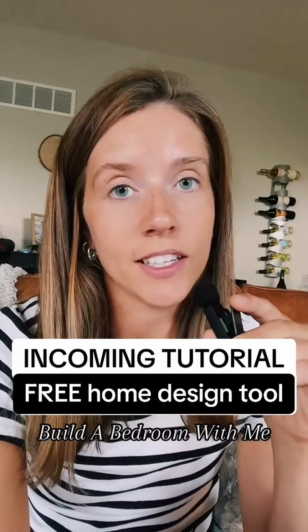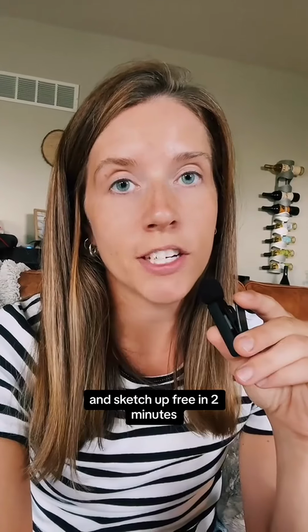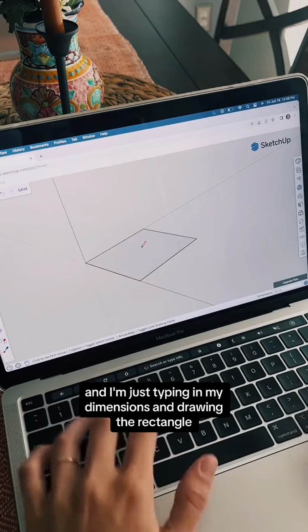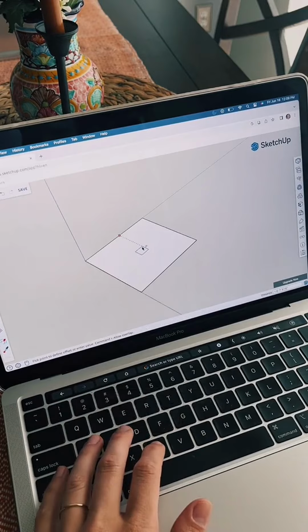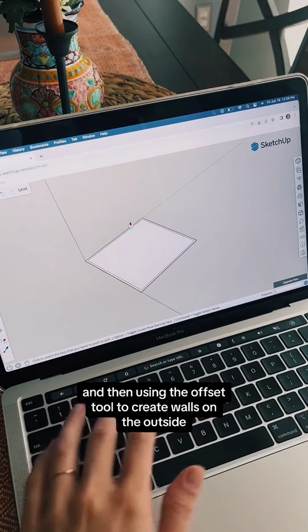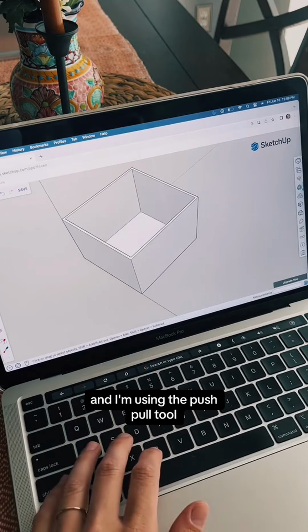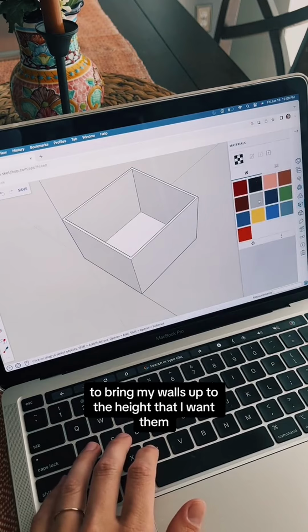I'm going to show you exactly how I model a 3D room in SketchUp Free in 2 minutes. Okay, so here we're starting with a rectangle tool, and I'm just typing in my dimensions and drawing the rectangle the dimensions that I want it. I'm then using the offset tool to create walls on the outside, and I'm using the push-pull tool to bring my walls up to the height that I want them.